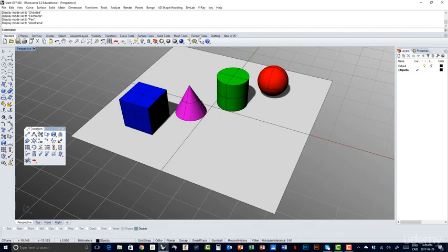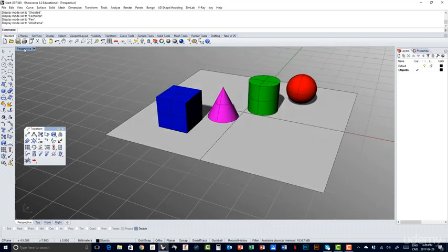You can see its name here. So basically you've got the move tool, you've got the copy tool, you've got the rotate tool, etc. If you remember, in perspective, I'm working on the XY plane, so I can take that cube, for example. I just left click it, I press move, and I can see that my cursor converted into a crosshair, and immediately I have to look into the command line, which is very important, and it asks me for the origin point to move from.